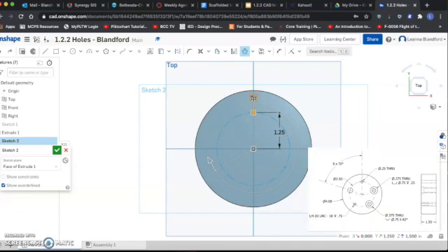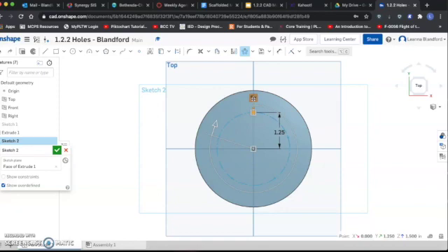If we look carefully on slide 10, we'll notice that we have a total of 5 holes. So I'm going to double click on this number 3. I'm going to change it to a 5, and I'm going to hit enter. So you'll notice that it extended the arrow a little bit, and now you'll see that next to your cursor, you have this funny little mouse with a green check mark on the left arrow. What that's saying is once you click, it's going to generate all 5 of these holes.